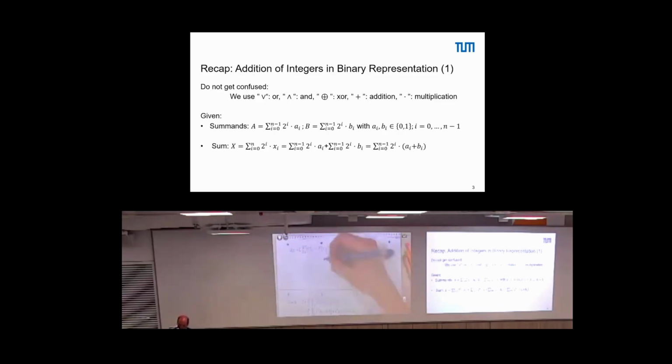Right? And then we can continue this until at some point we reach some full adder that has as input Cn minus 2, An minus 1, Bn minus 1, sorry. This one here is minus 2, the other ones are minus 1. And we have here Sn minus 1 and the output Cn minus 1. And since now there are no further additions, that's our most significant bit.